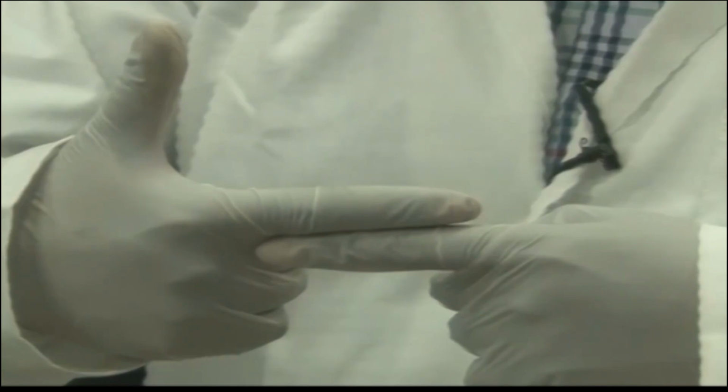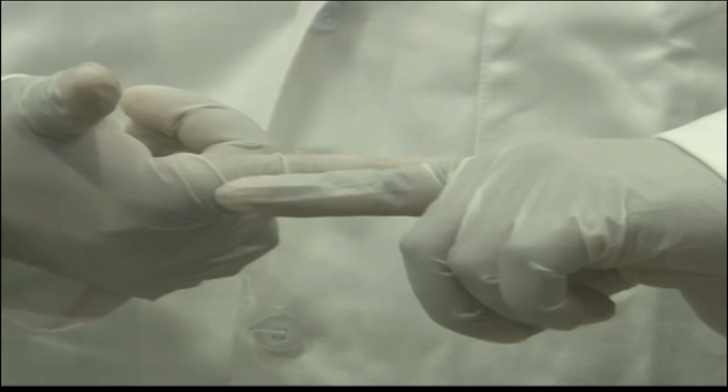What will happen? It will displace the nozzle. If this overlap is not here, this is 0.1 and this is 0.1, the nozzle will touch this one and it might displace the nozzle, the part might distort. So some overlap should be there, as there has to be some gap for the nozzle to work in. Some gap at this surface has to be there. So for that, this overlap limit is given. This overlap limit can be 15% or 20%.